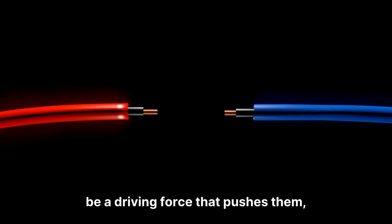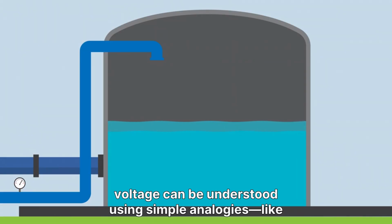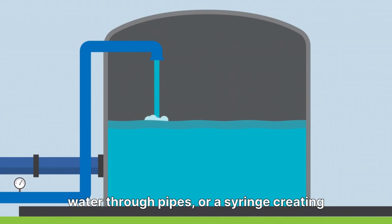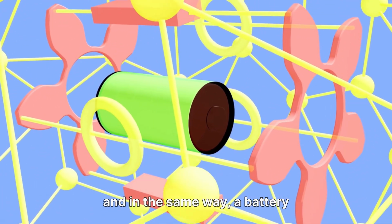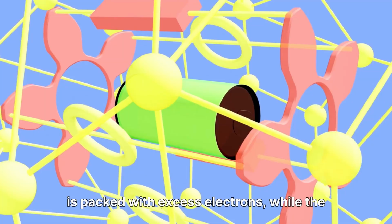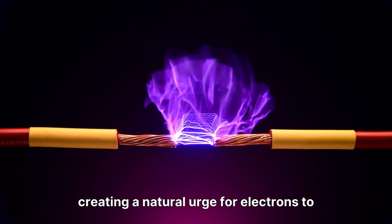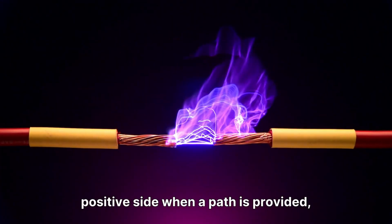But electrons don't move on their own just because a wire exists. There must be a driving force that pushes them, and that force is voltage. Voltage can be understood using simple analogies, like water pressure from a high tank pushing water through pipes, or a syringe creating suction when the plunger is pulled back. And in the same way, a battery creates an electrical pressure difference between its terminals. The negative terminal of a battery is packed with excess electrons, while the positive terminal lacks electrons, creating a natural urge for electrons to move from the negative side to the positive side when a path is provided.